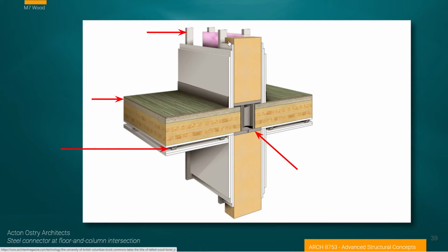So up here we have a large column, and then we have to double frame a wall here. That gives us great isolation between the units, but it also takes up at least what looks like a foot of space instead of 6 inches of space. Why they're triple laminating this, except for a very high fire resistant wall, I'm not exactly sure.